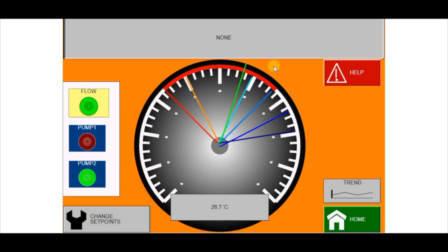So as we see, it's past the first line here that shows representation of the first stage of cooling, and the system status shows that Cool 1 has energized. You'll notice that the system didn't go into Cool Stage 1 immediately. There is a little bit of an on delay there, and I'll talk about that a little bit later on.